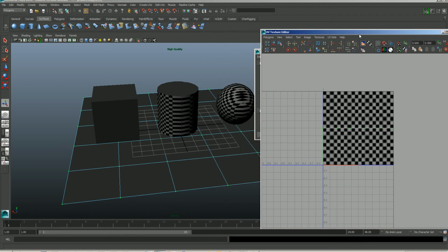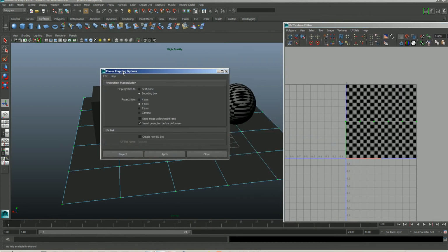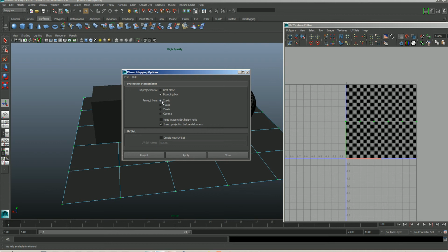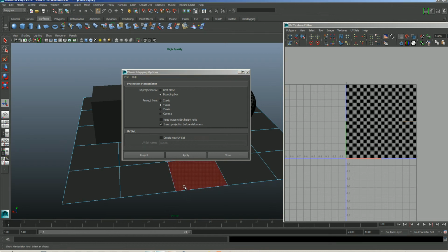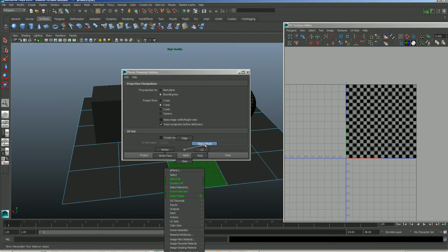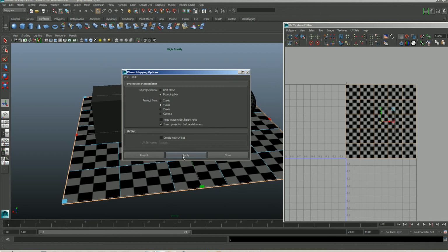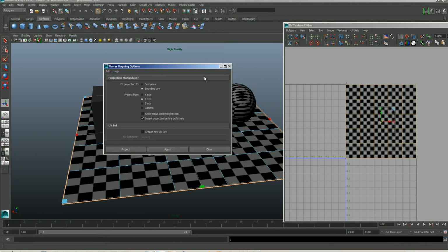And that's actually because of the way I did that planar map in the first place. What I did is did it from an x-axis. So I did it from the side instead of from the y. Equally, the z-axis would cause the same kind of problem there. So let's just click back on the y-axis. Make sure you go into object mode and apply that. And there, fixed.